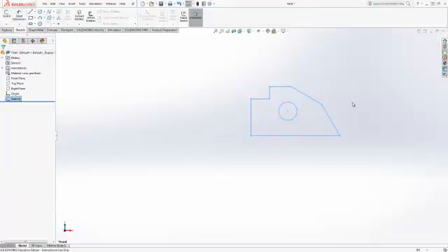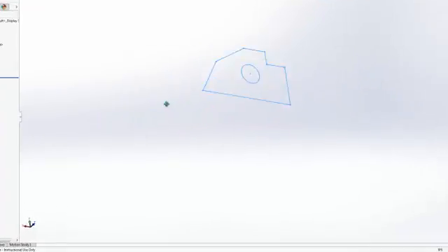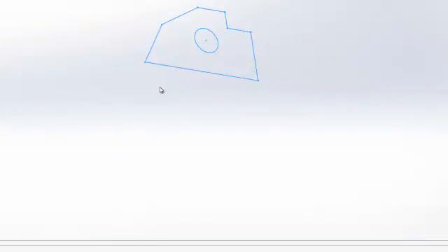Alright, now what? In this program, if you grab the center button on your mouse, notice that it does this. Basically you're orbiting, and it's hard to get things to line up. It's not like the view cube in the Autodesk stuff. But if you want to pan, you have to hold down Control and the middle button. I forget, and I end up messing up.